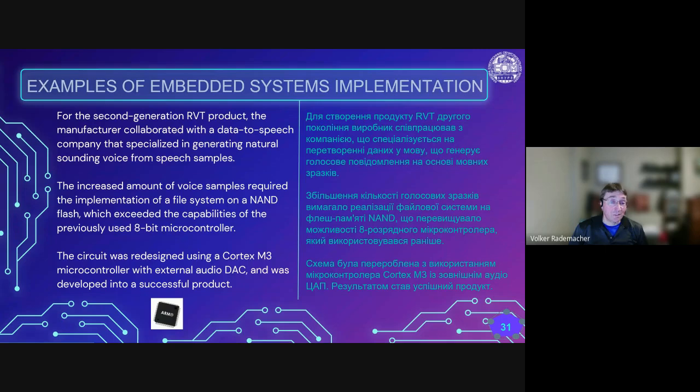So the result of this is that a wear leveling algorithm was required. So not just did the company need a larger memory storage, so it has to use a NAND flash, which is difficult to interface. It also needed to use a more complicated algorithm for wear leveling. This was also beyond the capabilities of a few developers.